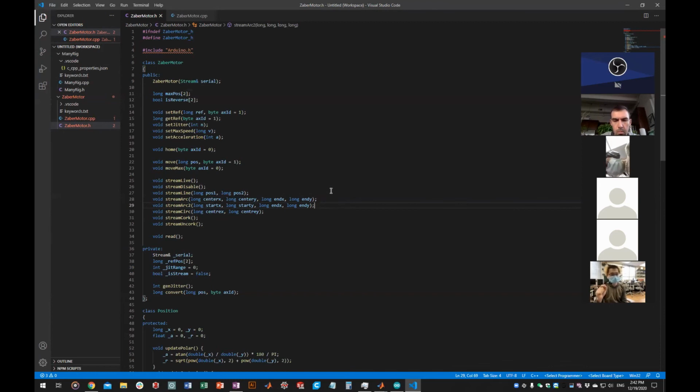You have to know which position you are at the moment, for example position index 0, 1, or 2, and you manually click P0 or P1 or P2 or P6 to make the physical location the same as the designated location. Then you resume the task, and things will continue normally. But that's a pain. I hope there's a better way to address it, but it is how it is right now.